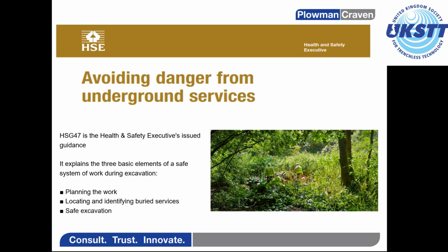Consider protective equipment, such as insulated spades, if hand digging is unavoidable, and ensure appropriate PPE is worn by all employees. We need to consider alternative excavation practices, so trenchless technology, no dig, vacuum excavation, the implementation of machine controls where necessary, and similar to reduce the risks.